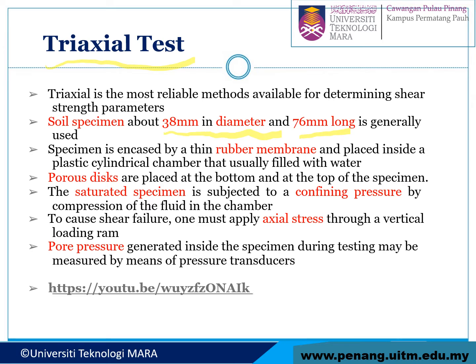Alright, the specimen is encased by a thin rubber membrane and placed inside a plastic cylindrical chamber that is usually filled with water. When we're talking about filled with water, you should know that of course it is related to pore water pressure. And then porous discs are placed at the bottom and at the top of the specimen. The saturated specimen is subjected to confining pressure by compression of the fluid in the chamber.